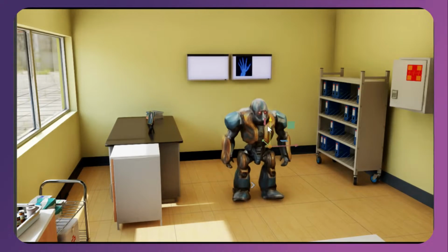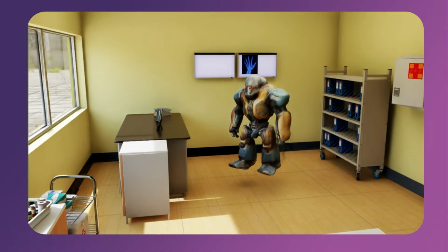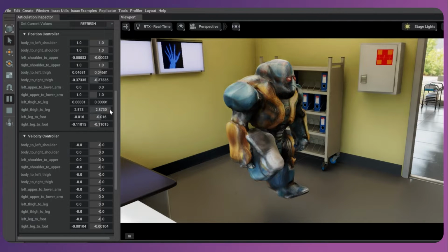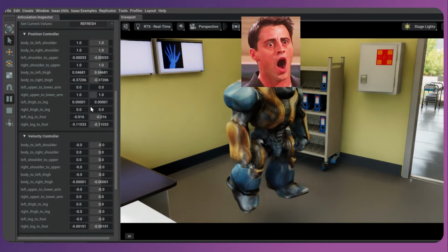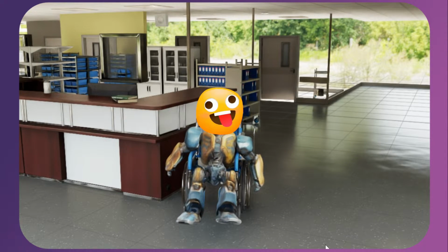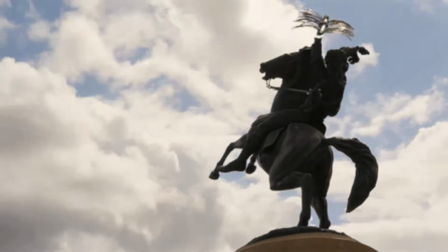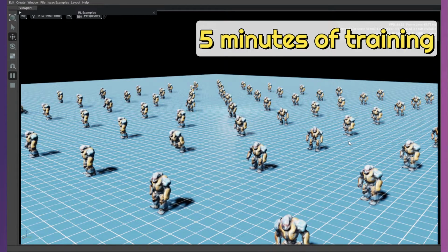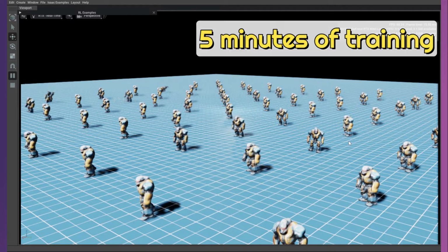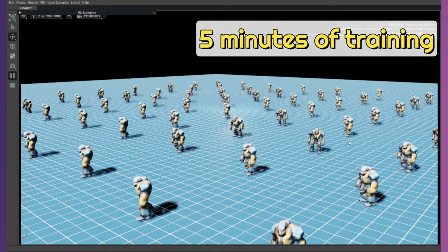The necklace humanoid could use another checkup on his leg joints. And it was quickly found out, his right knee was inverted, causing the shin to bend upwards. So, flip that problematic knee, and send him back to the training farm. Since I have changed joint definition, any prior training experience has to be thrown out. So reset the task and let it run another 5 minutes.